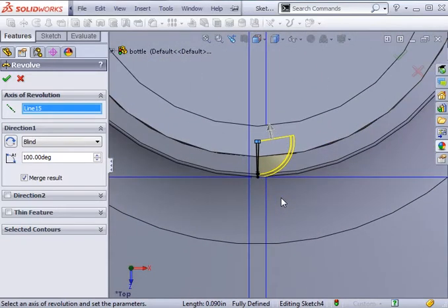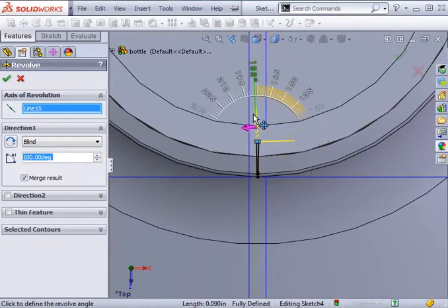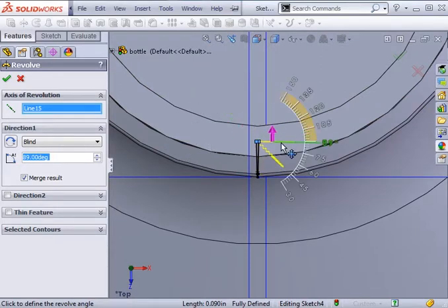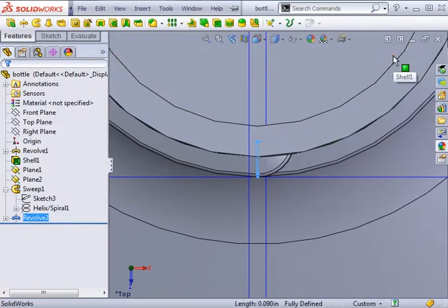If you want to make sure the revolved feature completely merges with the bottle, extend it well beyond the bottle surface, then as a second step, you can cut away any material that protrudes on the inside. This completes one end of the thread.